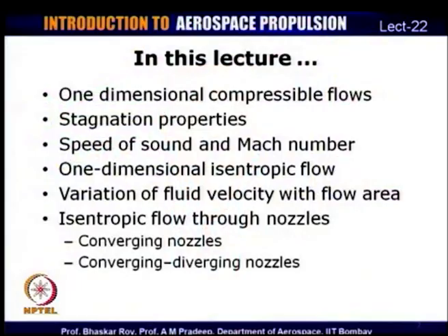In most of the day to day applications that we are familiar with, the velocities of the fluid are very low, and therefore, the inaccuracy that we incur because of assuming incompressible flow is not really high. Whereas, if fluid velocities are very high, then it is not really possible for us to make this assumption that the flow is incompressible.